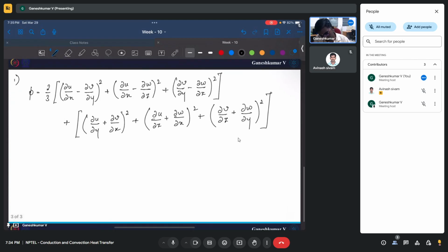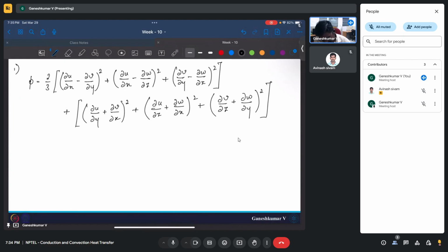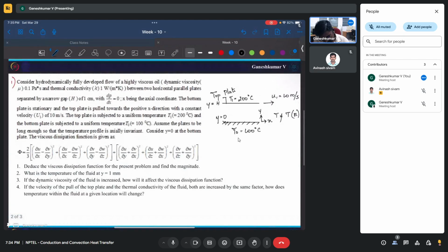Okay. Now in order to simplify this, we have to know u and v. For this case, we have non-penetrating boundary conditions in both places. Both of these walls are strict, there's a non-penetrating boundary condition implied at these two walls, which means the fluid cannot pass through. So ideally the velocity here is 0 and velocity here also is 0, so there cannot be any other velocity form here. So ideally the velocity is 0 everywhere, right?